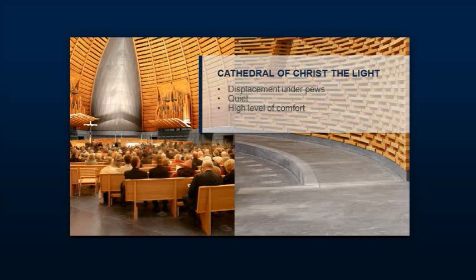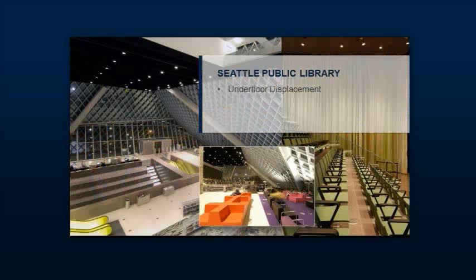So one interesting type of air diffusion you see in large bay areas like this commons area is nozzles. They are characterized by really long throws. They're a cool look. They're easily directionable. You know, there's nothing wrong with these devices in here. And actually, in this way, I'm not really mixing the area above those nozzles. I'm actually only mixing the floor to the nozzle level and a little bit above it. So I'm actually, in some ways, stratifying this zone.